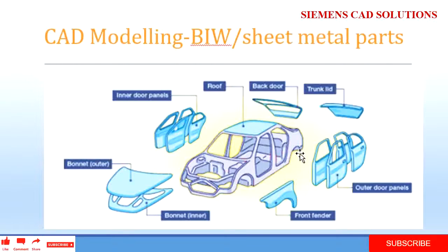So for BIW also they will get a surface, and then they will need to create the B surface. They will have the 3 layers of structure. So the BIW team needs to create all these 3. In BIW we will have the cutouts. So whatever plastic parts come to assemble, they will fit on the cut area.